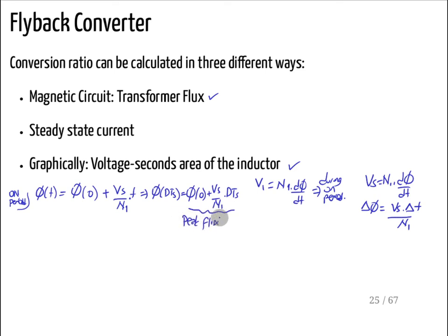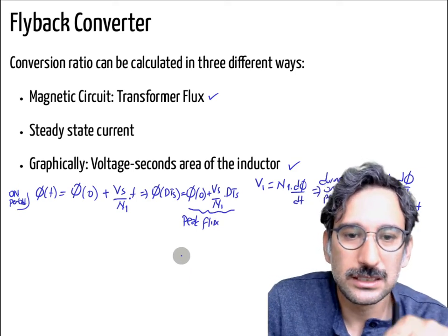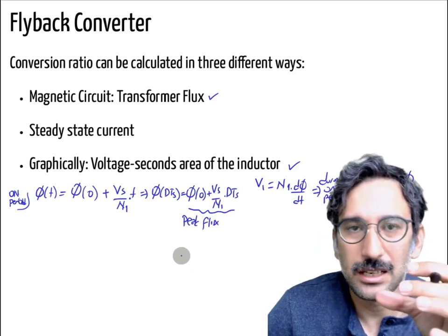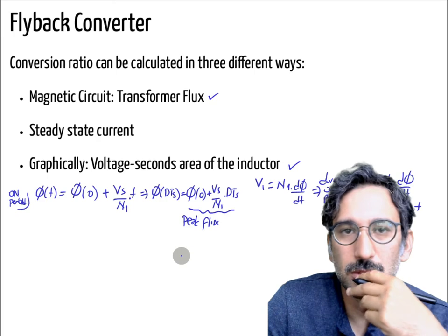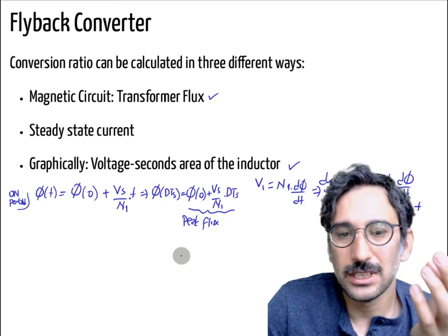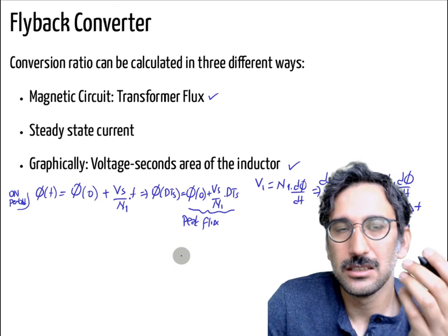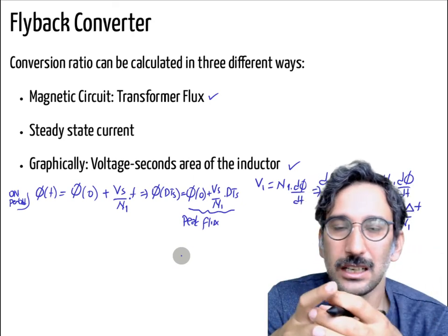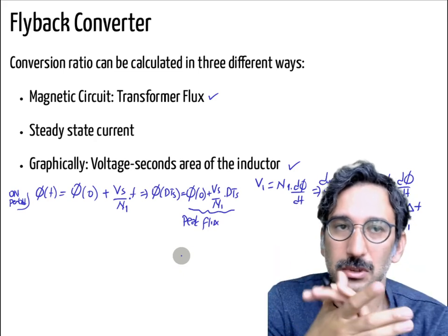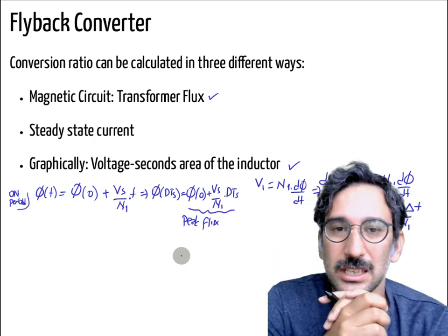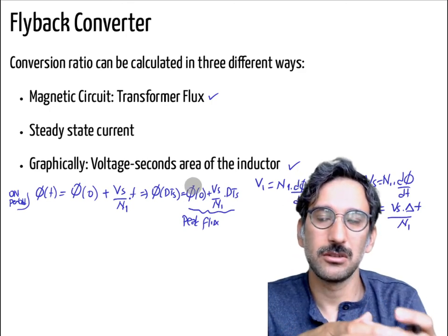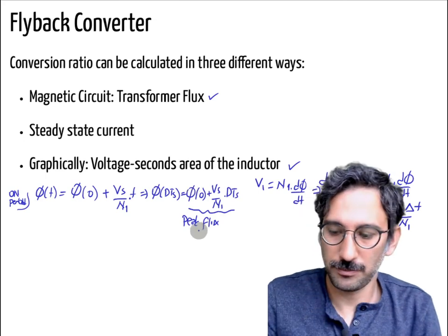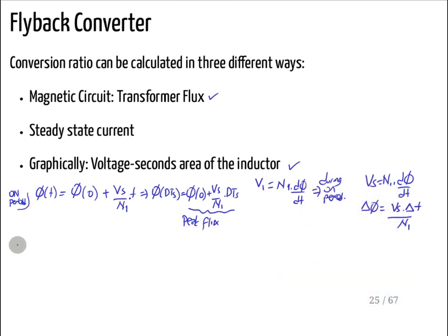That is important, because if you divide that number by the cross-section area, you can calculate the flux density. Once you start designing magnetic circuits, you will realize that if flux is large, you can't get a material with 10 Tesla or 100 Tesla. It has to be limited, let's say, within 1 Tesla. So if you would like to get a high flux, that means you need a high cross-section area for the core. Let's continue with the off state.